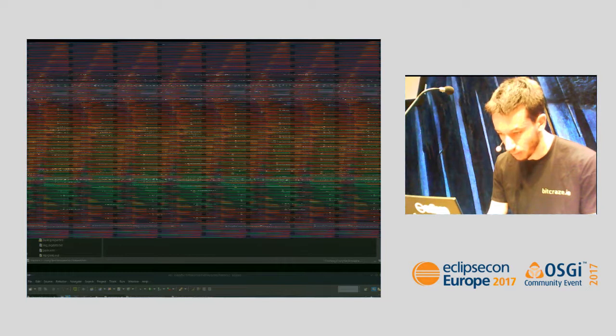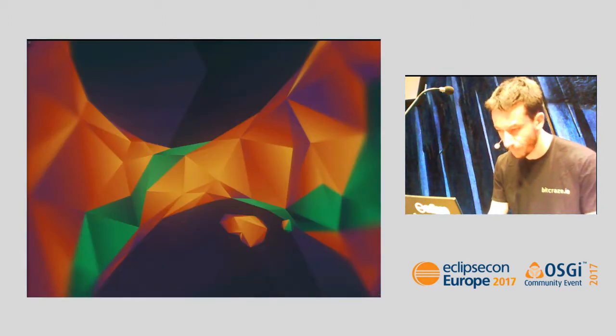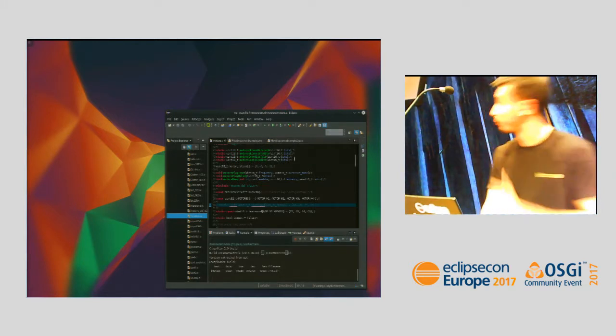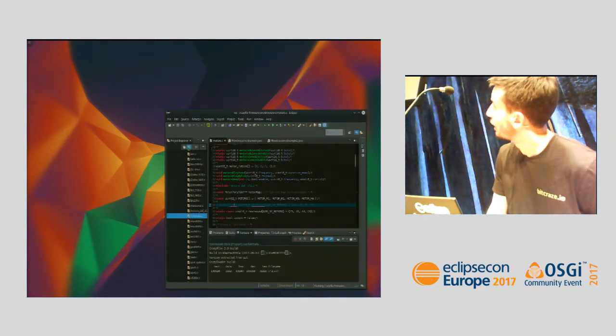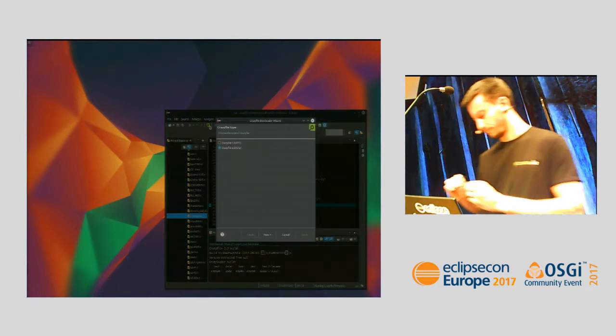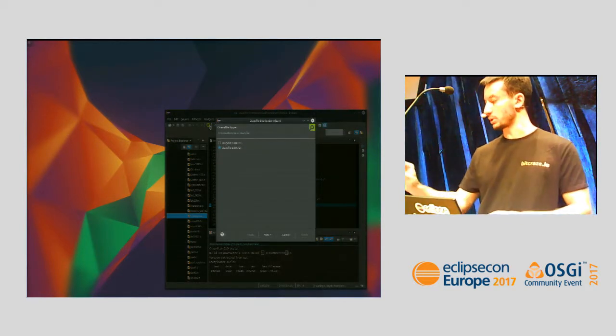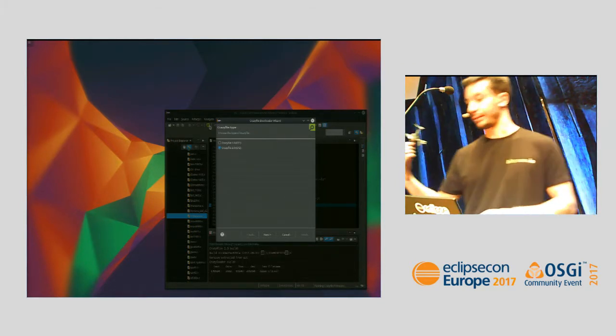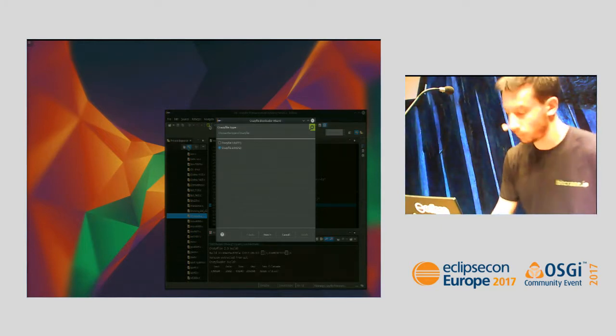Here, I enable the other one, and try to do it over here. And I will run the build. So the firmware file is generated. Now I use the wizard. What I have to do first is put the Crazyflie in bootloader mode, which is done by pressing the button long. Now it's blinking two blue lights, and it's in bootloader mode.